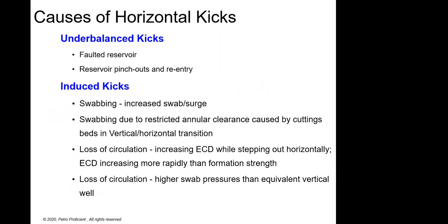There are two types of kicks that can be considered. One is the underbalanced kick, which we just spoke about, but it can also be caused by a faulted reservoir, where the pressure might suddenly increase and your mud system does not have enough hydrostatic pressure to counter it, so you become underbalanced.